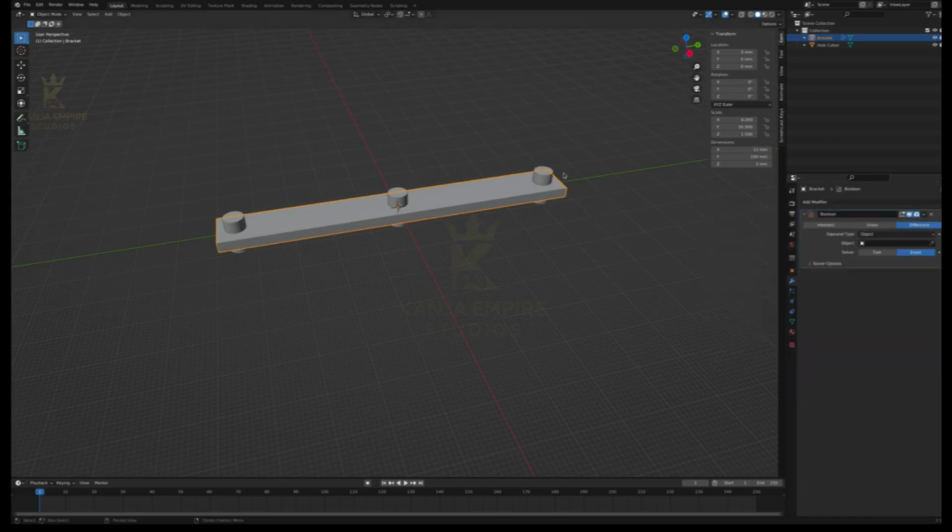And it's pretty standard for applications that use meshes, and when we're designing things, these are meshes. So all you have to do now is select the object, select hole cutter, and make sure it's set to difference. That's the subtract, so it'll subtract the cylinders from the bracket. And go ahead and select this drop down and click apply.